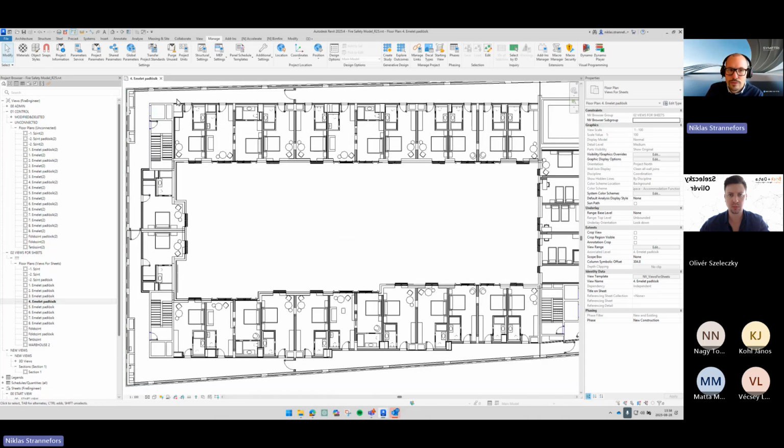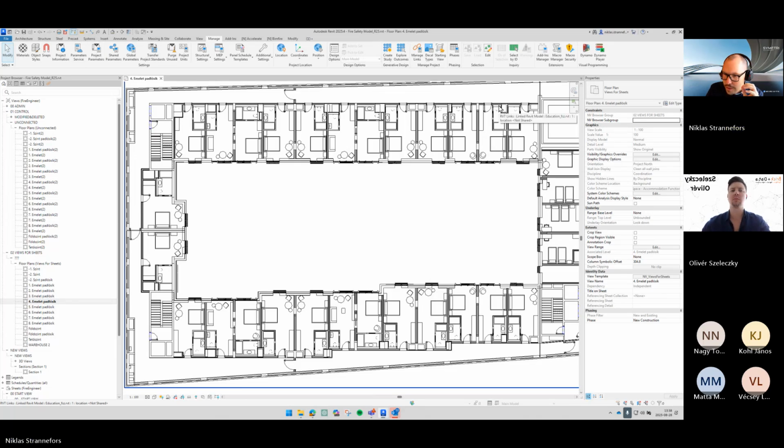I want you guys to go around and place a wall requirement around the hotel walls in between each one of these. Any kind of requirement, whether it's EI 60 or REI 60, mix as much as possible. And I want you to place a door requirement on each and every one of these doors, and obviously those sections.